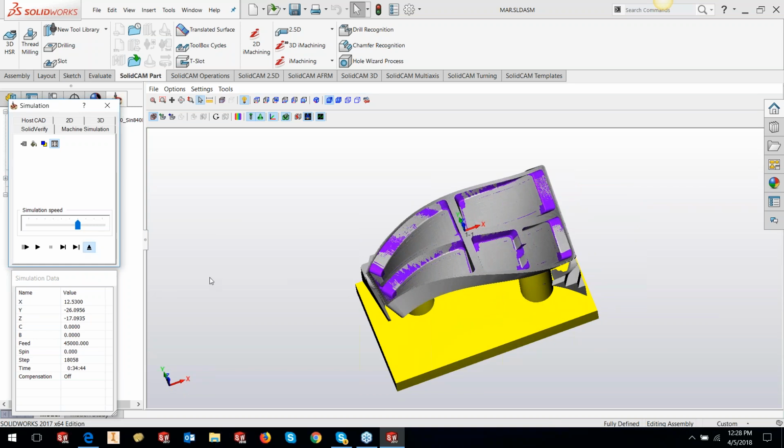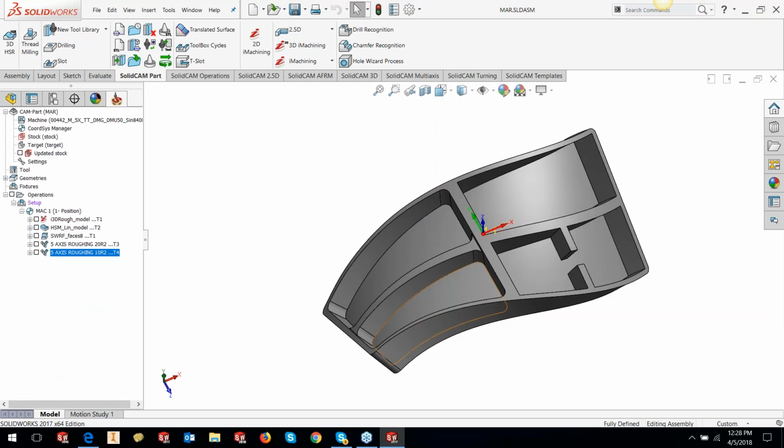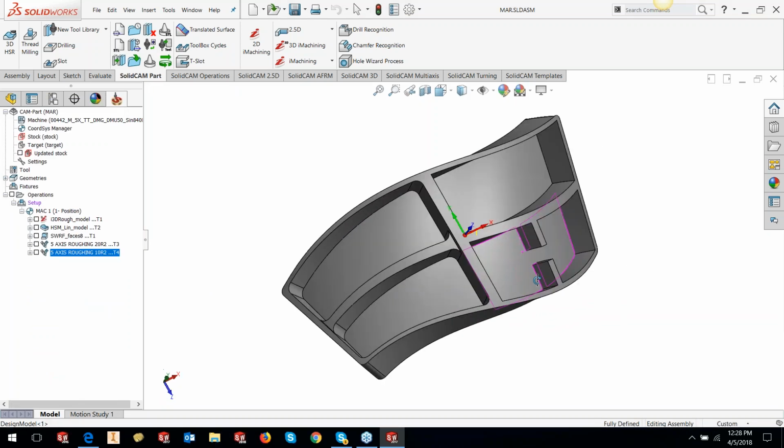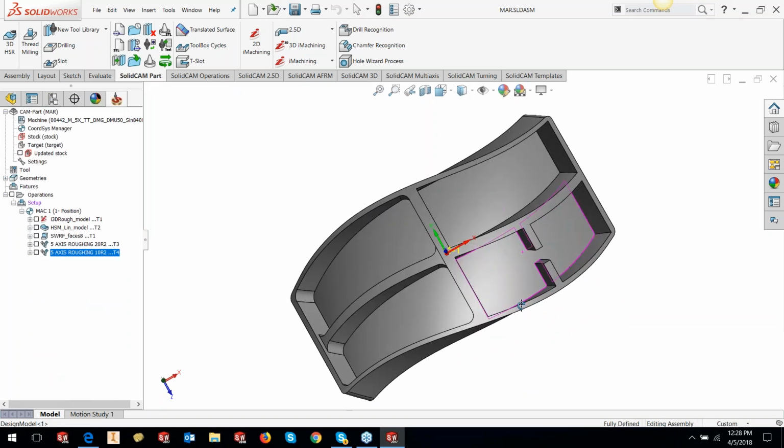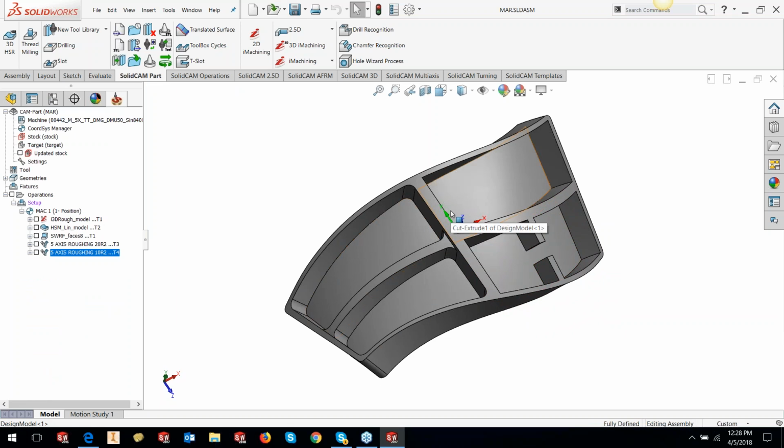All right. So, like I said, SolidCAM's multi-axis roughing can be used to rough out parts like you're seeing on the screen out here, where the tool axis will always be normal to the floor surface, and it will cut the adjacent walls in that particular tool axis only. So you could have a situation where, if your wall is not normal to your floor, it could either leave material at the bottom or the top, depending on how the wall surfaces are.